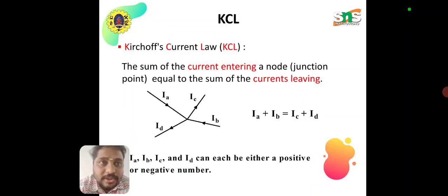Coming to Kirchhoff's current law, Kirchhoff stated two laws, that is Kirchhoff's current law and Kirchhoff's voltage law. This is the first law, Kirchhoff's current law, KCL. The sum of current entering a node or junction point is equal to the sum of current leaving. The incoming current is always equal to the outgoing current.